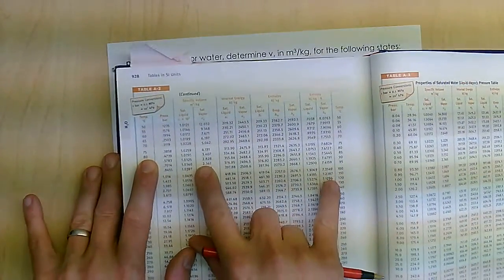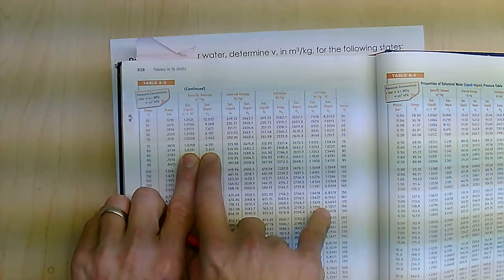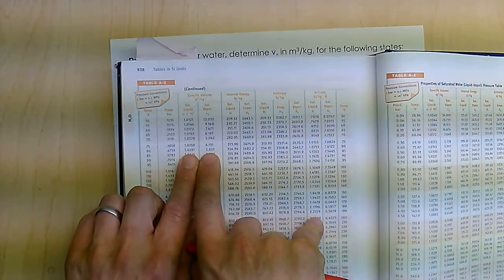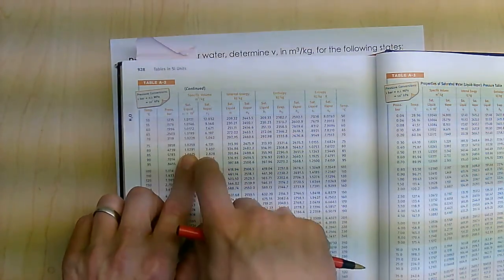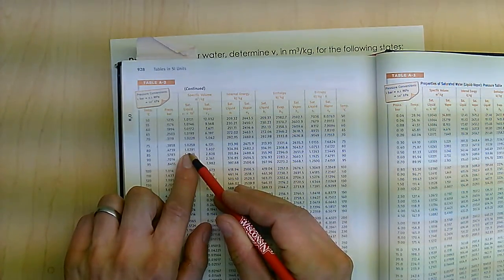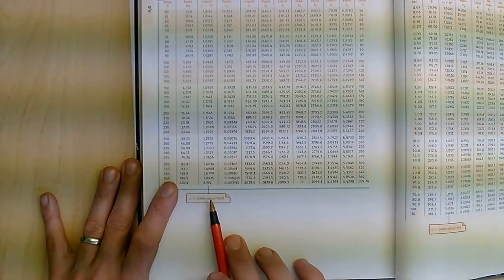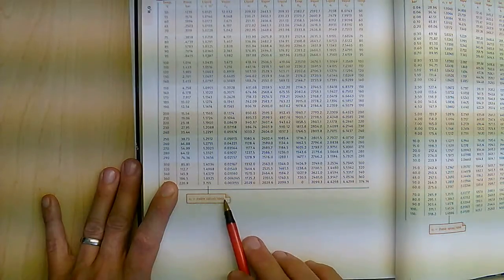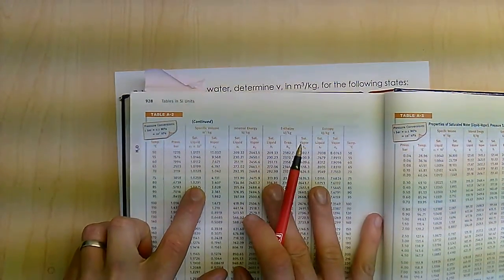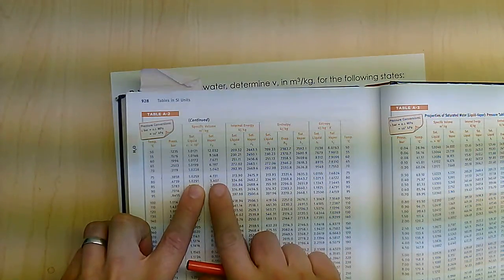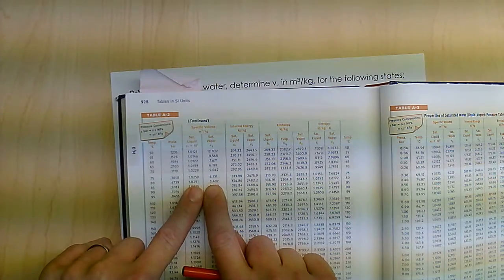So at 80 Celsius, you can see that my specific volumes are between these two points right here. The way this is written, with the volume times 10 to the third, that actually makes this 0.001029. And if you look at what it says down here, it's a table value divided by 1,000. So at saturated liquid, the volume is this. At saturated vapor, the volume is 3.4. I'm 75% of the way